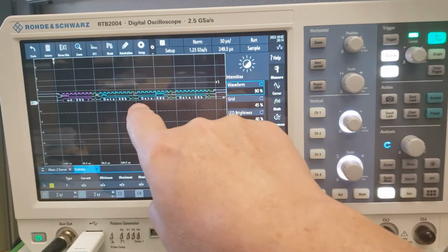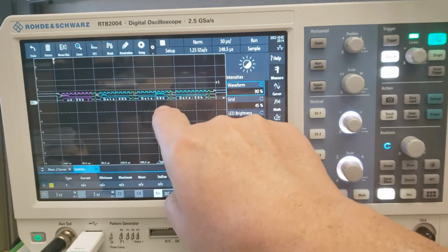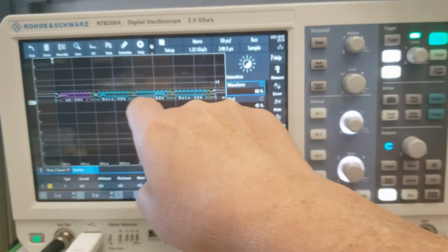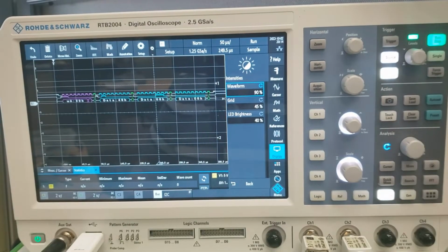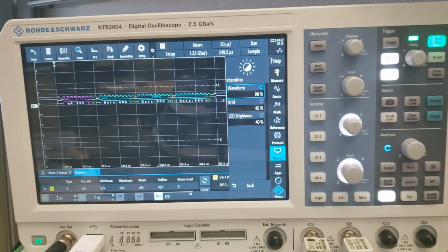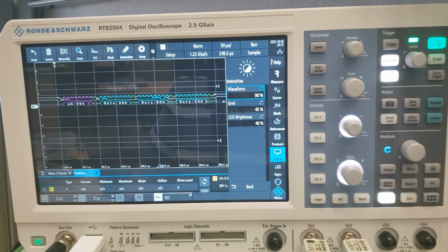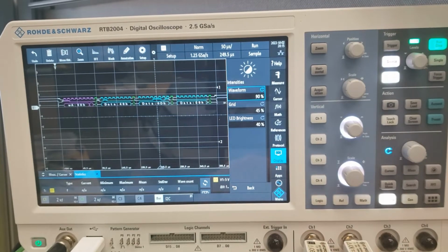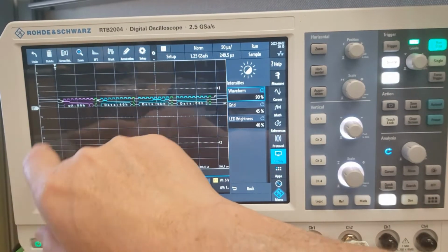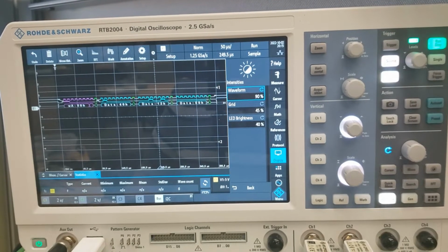And what's really neat, I haven't seen this before, especially on the picoscope, it's showing you the decoded information as well as the digital signals that you see up on top there. Okay, it's taking the information from the analog input, converting it to digital, and displaying it. It's even indicating the acknowledge and write conditions for the I2C bus. So really useful.